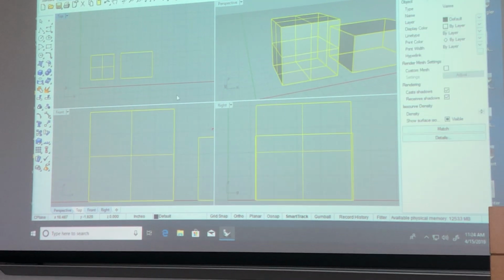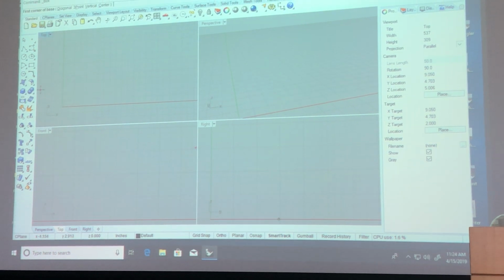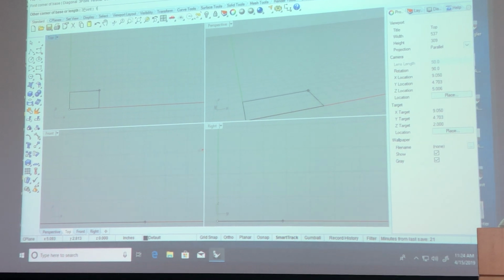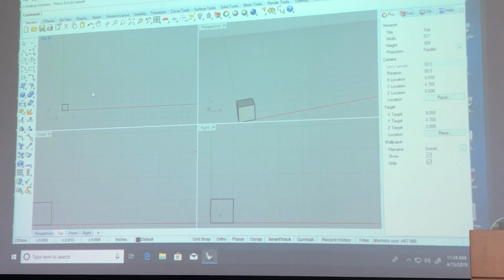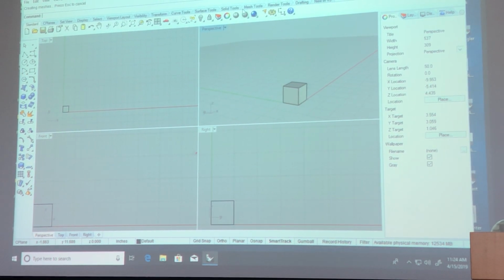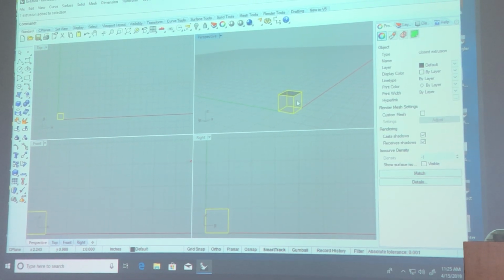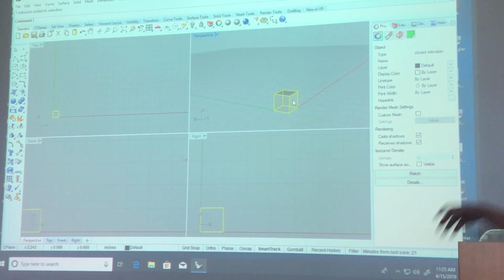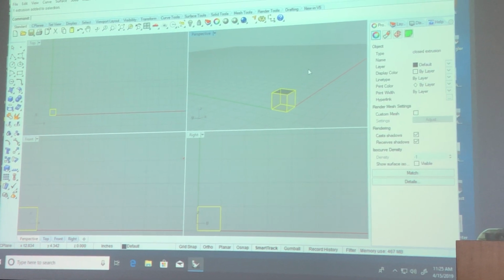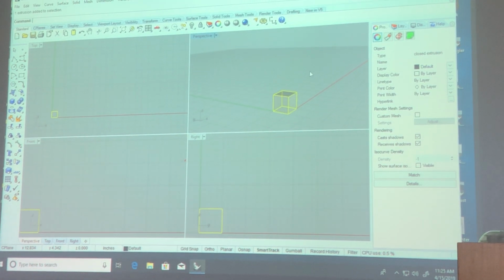But hey, fun. Here's what we're really going to do. We're going to make a box. It's going to be a little tiny box. I'm going to start at 0. I'm going to make it 1 inch by 1 inch by 1 inch. It's a cube. It's so exciting. So when I click on that, the box is a closed extrusion. Great. I want to 3D print my little cube. I need to export it correctly, but first I need to make sure that it's that.